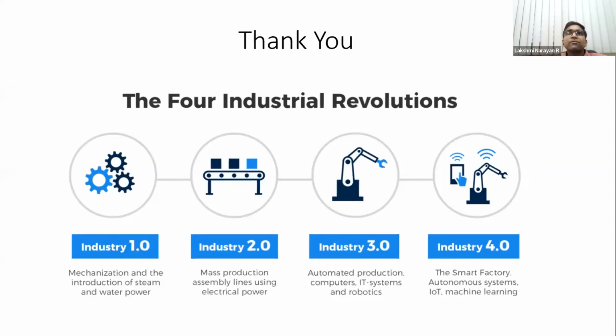We make sure that, of course, niobium will segregate, and that could be a problem. But we maintain the flow to some extent so that niobium does not pile up at the bottom. So the flow has to be adjusted to such an extent that niobium and zirconium 50 are melting and fusing, or rather, both are not melting. Zirconium 50 is melting and niobium gets embedded in a reasonably homogeneous fashion. Of course, full homogeneity is not ensurable because of the irregular shape of the niobium particles. But if we keep the melting volume low, we can ensure a reasonable degree of homogeneity. So that is how we tackle it in LDED.